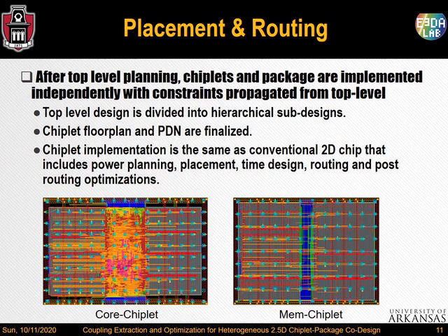The figures show the finished physical design of the core and memory chiplets. Their floor planning, power planning, placement and routing are performed using standard 2D chip design tools.